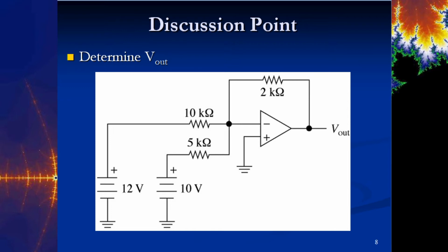To start our talk about the op-amp, the first thing I'm going to point out is that we are going to assume there is a very high input impedance between the two terminals here. This is essentially set up like a comparator. So very, very high input impedance on the front two terminals, and we can assume it's nearly infinite. That means this becomes essentially a virtual ground. I say virtual because it can't sink current like this ground can. So this is a virtual zero.